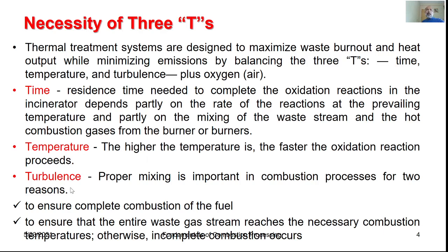The third T is turbulence. Here, proper mixing is important in the combustion process in order to facilitate the proper supply of oxygen, which is entering as air, to facilitate complete combustion, as well as neat exposure of the surface to receive this higher temperature to ensure faster oxidation.